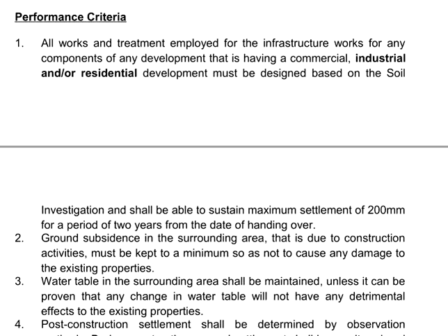The developer can choose to have the infrastructures such as road and drain supported by the suspended system, and in this case, this has totally eliminated the risk of having settlements of more than 200 mm in 2 years, as the suspended systems are typically supported by deep foundations. Now, the problem with the suspended slab system will be the cost of the construction. This will bring direct impact to the selling price of the building units.